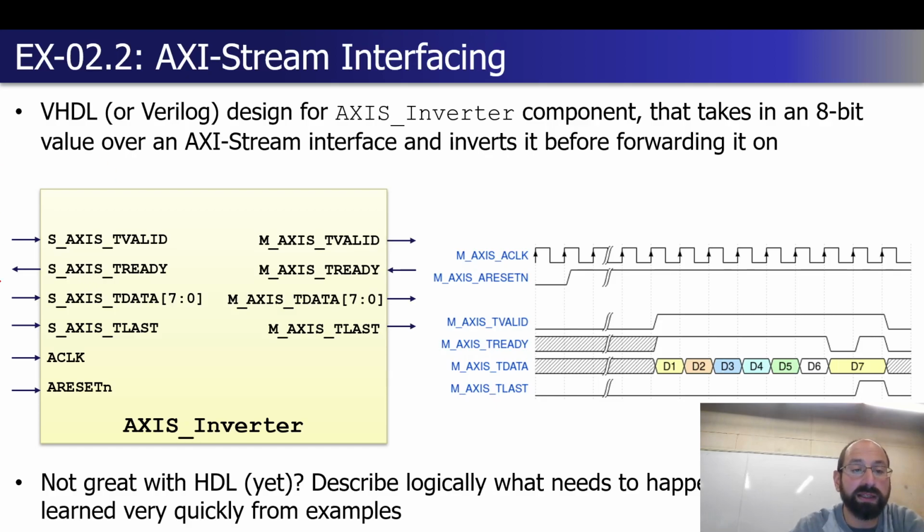Let's start signal by signal. I know I have valid data to send when this signal is high. When is this core ready? When are we ready to send something or to receive data? Pretty much always. I would agree with that. This core shouldn't be the cause of any stalls, right? I mean, you can imagine it's buffering and doing some complex math, but this isn't. This is just inverting it, right?